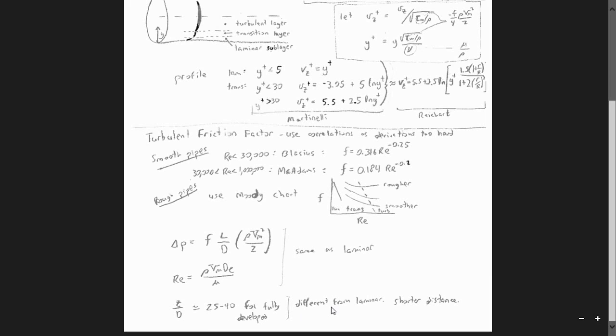And then I just note that we've been considering only fully developed flow. So the actual entrance to the nuclear reactor's core, where the fluid first starts to flow up the fuel pins, will not be fully developed. However, that distance is fairly short. We typically do have a turbulent flow in the nuclear reactor's core, and we're going to be arriving at fully developed flow somewhere between 25 and 40 centimeters, given the diameter of our tubes is about a centimeter. So fairly short distance compared to the multi-meter length of the fuel pins.